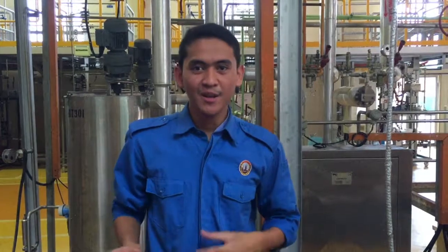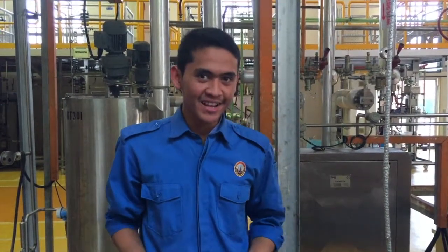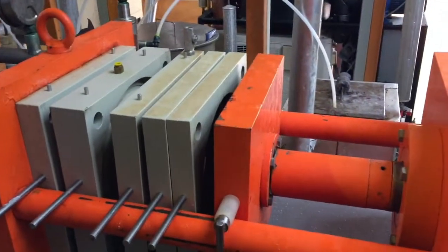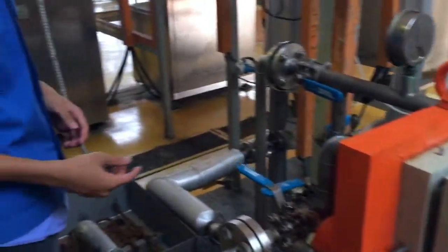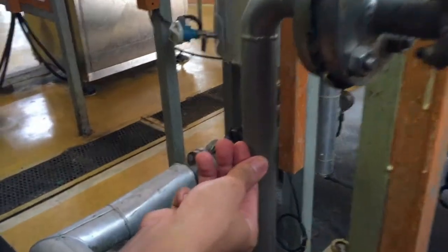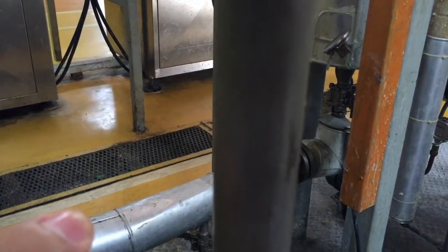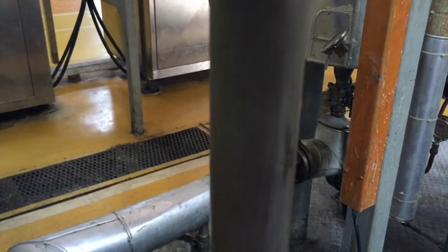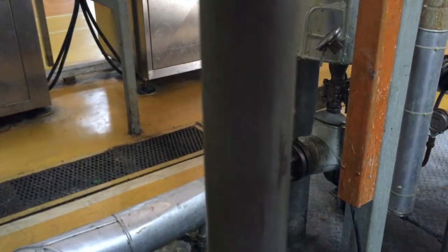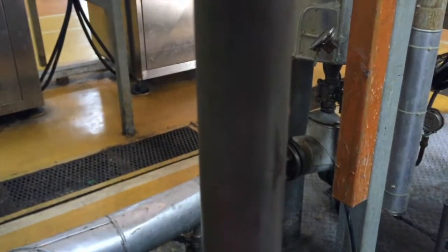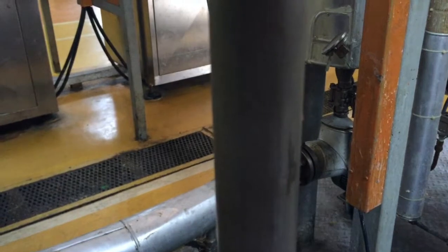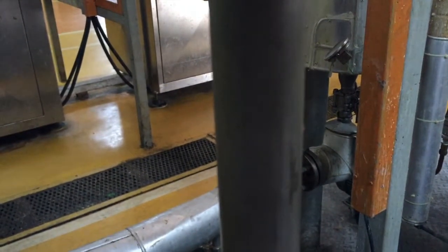Okay, so here the method of magnetic particle inspection can be applied directly to the filter press. Here we have our filter press, and let's figure out the line of cracks. This is actually the point of discontinuity. In order to determine it, first we apply a liquid containing magnetic particles on the surface. After that we use a magnetic field, which will cause the magnetic particles to migrate to the surface of cracks, and lastly we visualize under fluorescent light to better see the point of discontinuity.